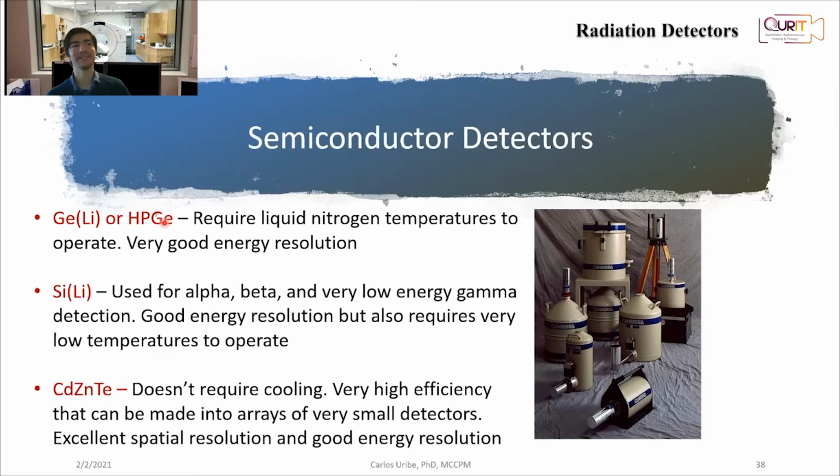It's being used though, but it's expensive. So another option to deal with those impurities in the crystal that are taking some of our electrons is by introducing impurities that do the opposite. Those impurities will donate electrons. And that's why, for example, we have lithium. So that's why you have here germanium with some lithium, silicon with some lithium. So we're in a way trying to compensate for those impurities by adding lithium. And what lithium is going to do is that it's going to give us some electrons to compensate for those electrons that those traps will be losing.